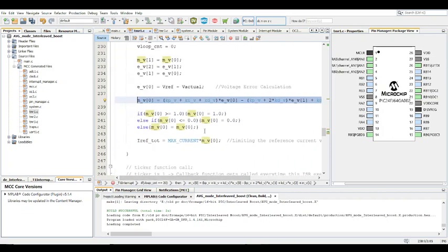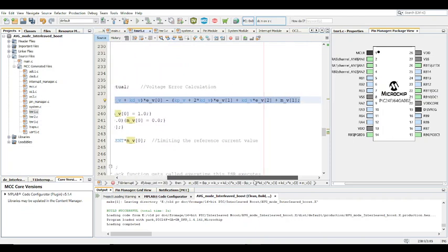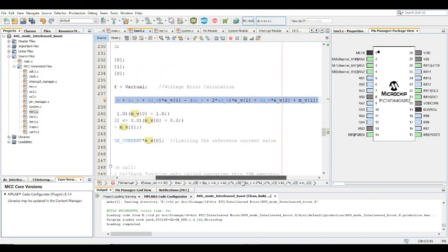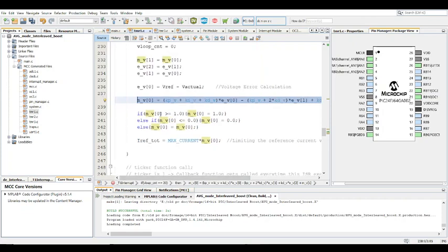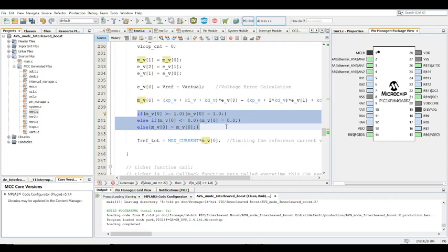And then after, it essentially has some similarities with the position form PID control, but this is a velocity form, and it works much better for digital power supplies. All right, and then after you compute that, just look at that document, it will make a lot more sense. But anyway, that's how you get the PID step out.